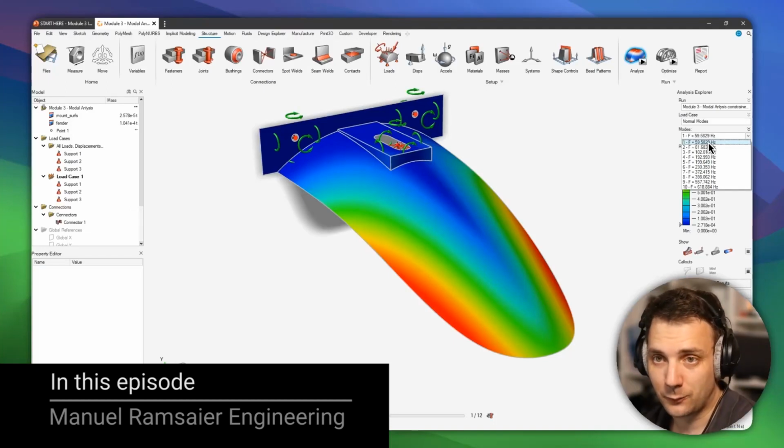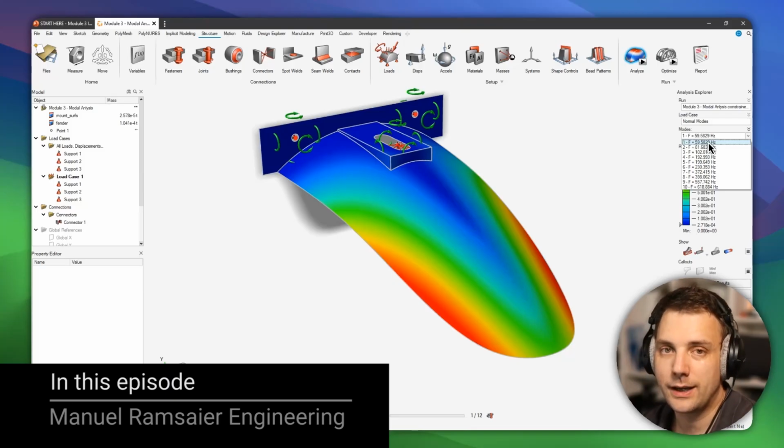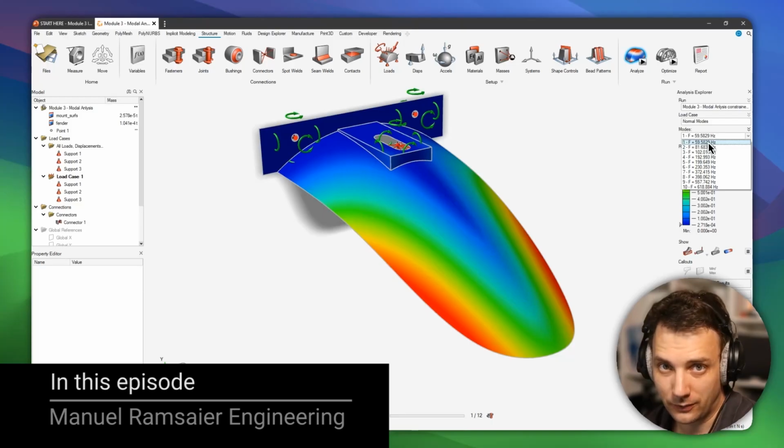One, you have the frequency. The frequency is one output, and that's the frequency where this eigenmode happens. The second one is the eigenmode itself, or the eigenshape, or however you would call that, is like the way the part deforms at that eigenfrequency.